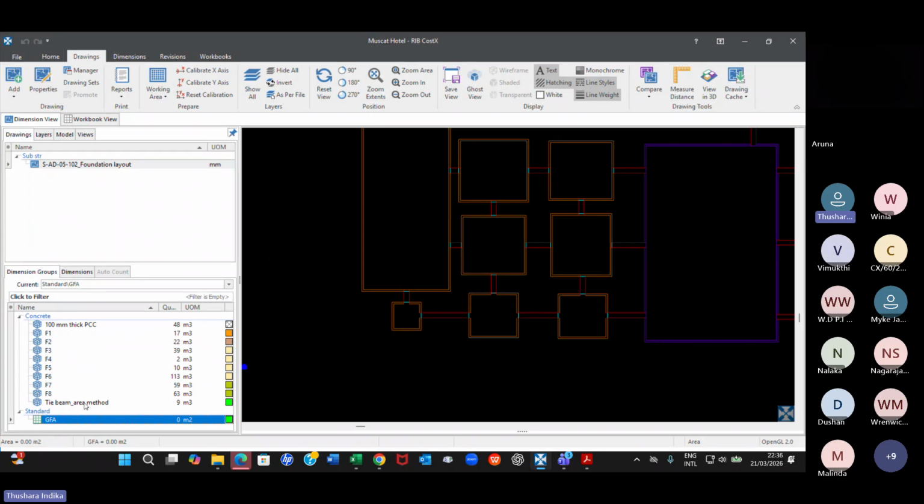So likewise you have to define each TB, the dimensions, because sometimes 0.5 thickness, sometimes 0.75, sometimes 0.4 or whatever. Depending on the size of the tie beams, you have to define the dimension groups again. I was able to do it in one go here because all the tie beams are the same size, so I measured all of them in one dimension group.